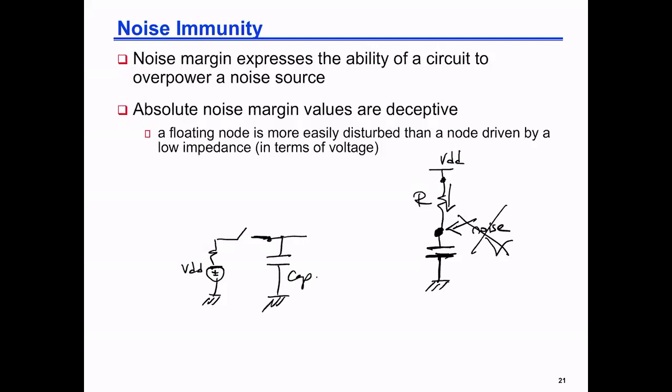And all of a sudden somebody pulls the charge through a noisy path, or it gets coupled or affected somehow. After the noise source goes away, after the noise withdraws current from the capacitor, will anybody charge the capacitor? No. So this we call a floating node.